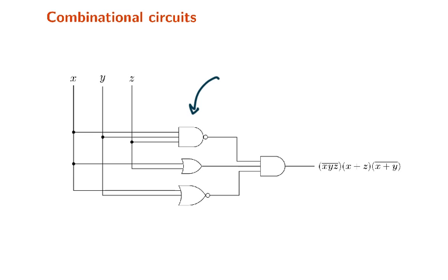So this gate originally was an AND gate, but has a NOT, so this is called a NAND gate. What it means is that the inputs are going to enter in the AND gate, and by having this NOT here, we are going to do a complement of them before they get to be an output.